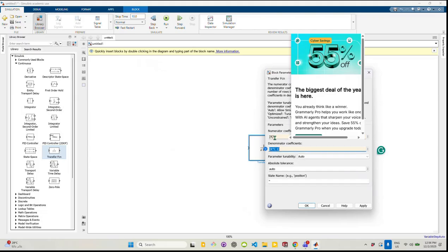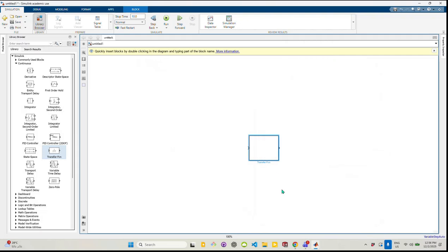This means now the Simulink understands what the values of R and C are. So click OK, and you will see that this is going to update as well. If, for example, you make it small, then you will see numerator and denominator. If you zoom this box or make this box big, you will see R and RCS plus 1 explicitly shown.